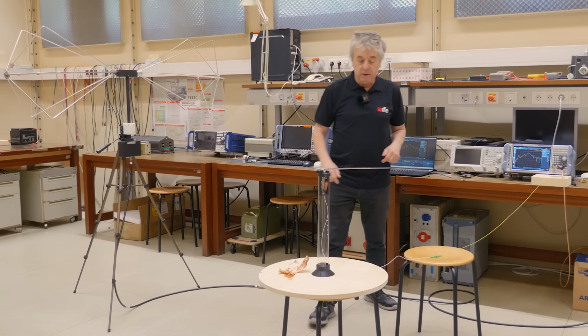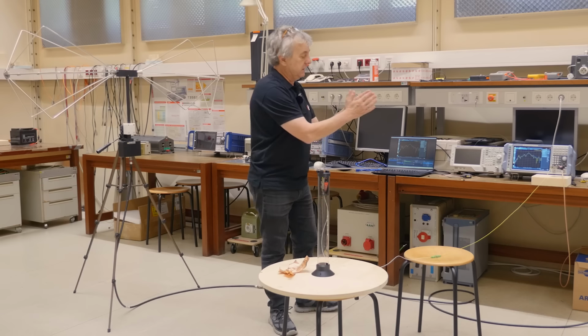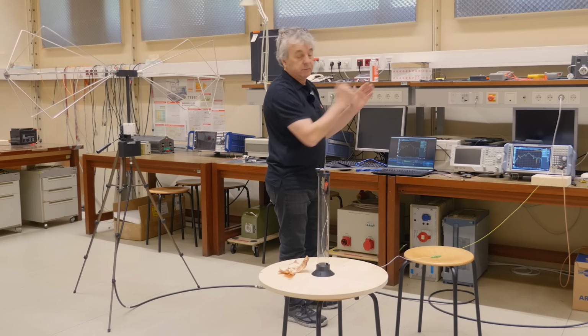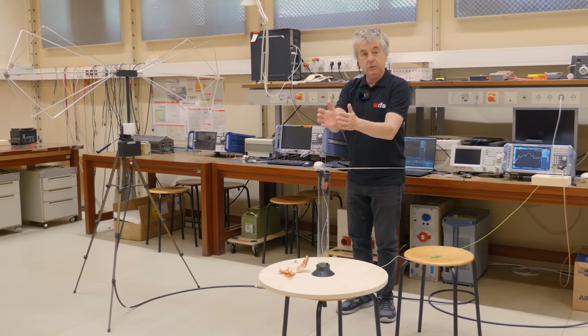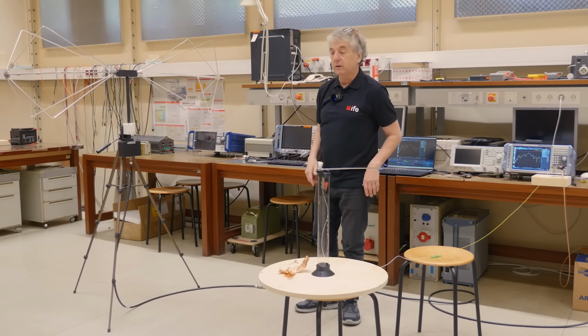The other experiment is we put both antenna rods in parallel, so they form a differential signal. So they go in this way if you look at the currents. Now the receive antenna will see both from here and from here, but they're out of phase, so the signal is significantly reduced because these two currents cancel.